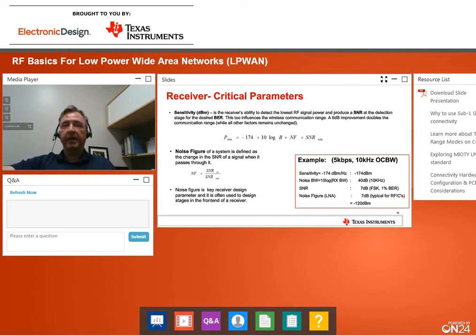If you have just a 50 ohm resistor and you hook it up to an LNA, it will have a certain amount of noise energy. This noise energy is typically denoted as minus 174 dBm per hertz. This is the noise energy that an antenna will have all by itself at room temperature.